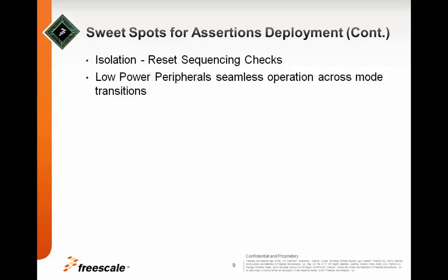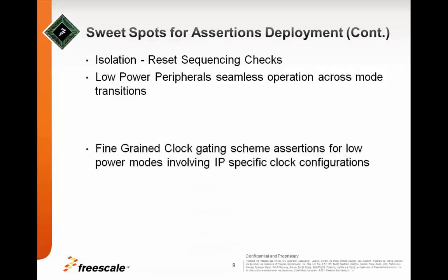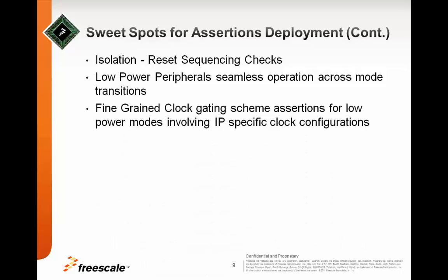In our SoC design, there are certain low power peripherals such as SPI, FlexScan, etc., which were required to operate seamlessly across the low power mode transitions, and thus it is required that the resets to these peripherals are not asserted or deasserted during the mode transitions. Again, we successfully deployed the assertions to check the reset behavior for the low power peripheral seamless operation.